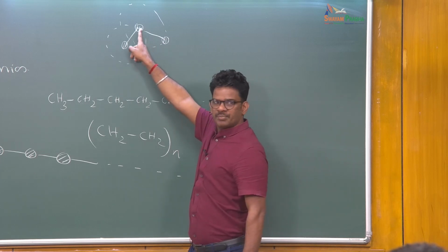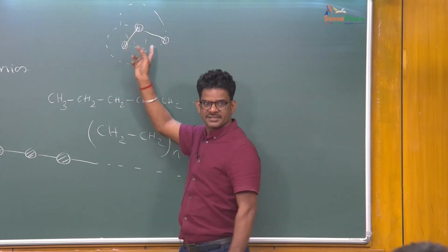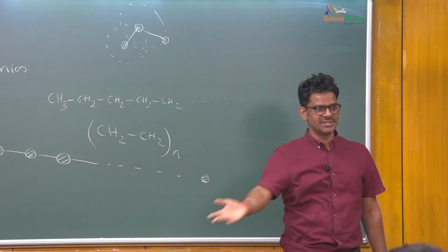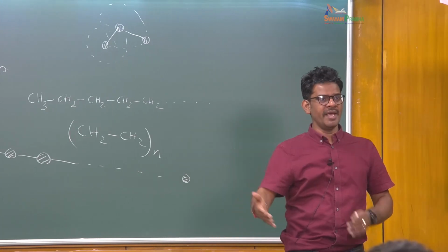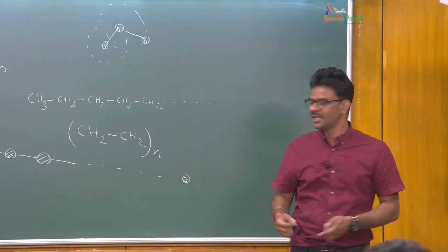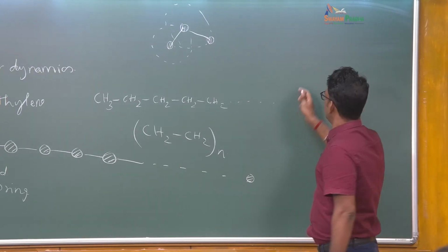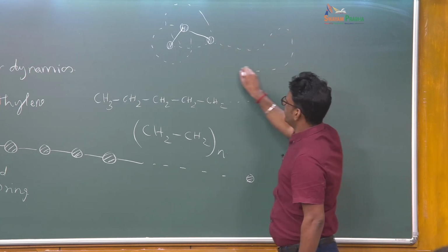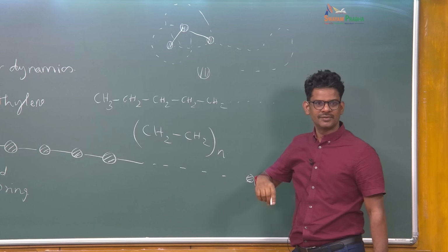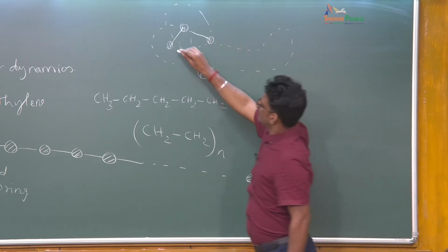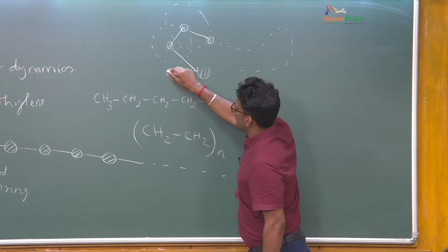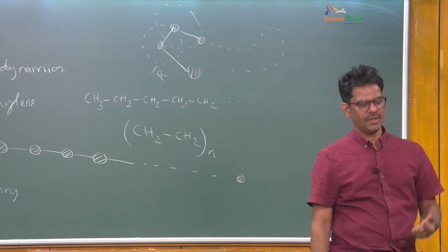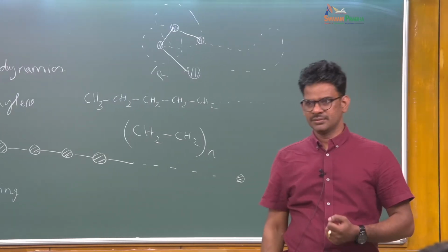Once this position is obtained, then this molecule can relax to find its own place. And then when you have a number of repeating units of the order of hundreds and thousands, you can see how many independent ways each of these monomers can take position. And once you execute this, so this is going to be extended, and the final one probably can be somewhere here, we don't know, because there are so many possibilities. Now we are asking what is the end-to-end distance vector r, and what is the distribution of that? Okay, is it going to be a certain value or is it going to be a random variable? That's the question we are asking.